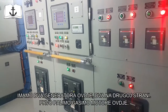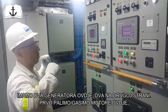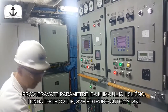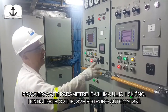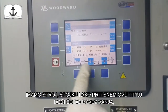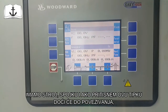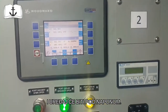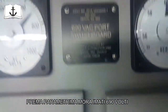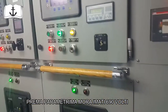Yes. Basically it's built like this: you have two generators on one side and two generators on the other side. You start the engine first, then you load up the engine properly. The next step is checking the parameters in the engine room, that the engine has the oil and everything it needs. Then you come here, and it's a fully automatic system. You just push the button and you can connect the power. It's like an engine clutch, as we call it, but basically it's an electrical connection to the breaker. When I push this button, the breaker will be charged, and then we have the energy. You have all the parameters there. It must be 690 volts, we have 60 hertz, and the amps are according to the current we take.